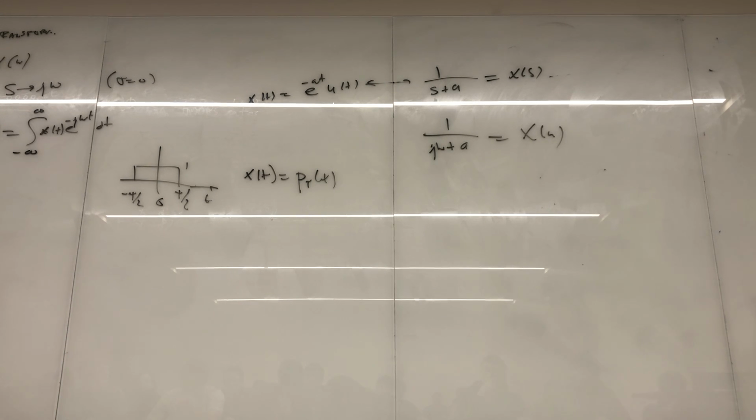But here's the beautiful thing. About 99% of the functions we deal with, maybe 98%, usually have all their non-zero information from t equals 0 to infinity. So the idea is this: if you know the Laplace transform of something, good chance you know the Fourier transform by just taking s and replacing it by j omega. Does everybody hear me? Really important to get this.